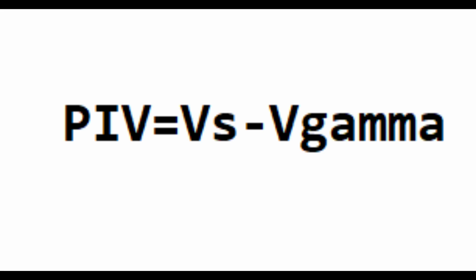Finally, to find the peak inverse voltage that each diode must sustain, we use the equation peak inverse voltage equals the voltage reverse max equals the voltage of the secondary max minus the diode cut-in voltage. So we get 6.4 volts minus 0.7 volts equals 5.7 volts.